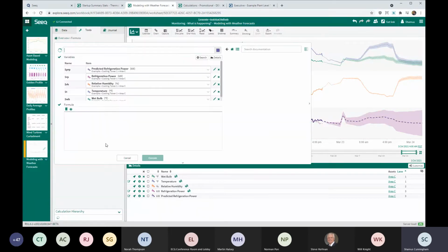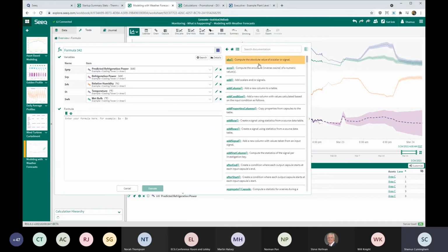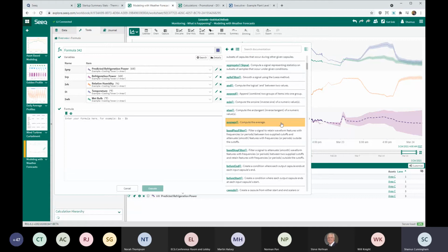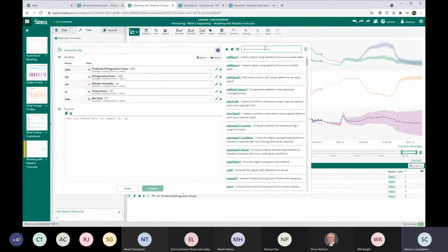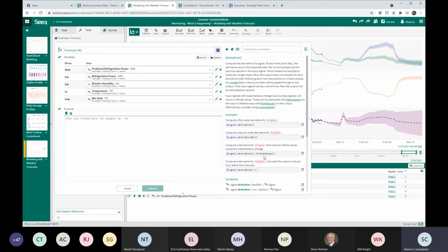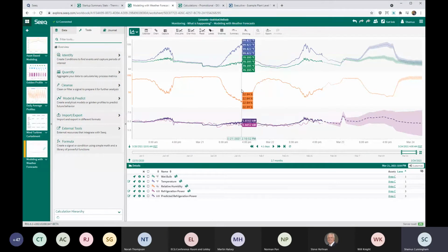we realize we're not going to build point-and-click tools for everything everybody wants to do. And so we also have a really nice formula language in here that codes exactly like Excel and has about 300 different functions that everyone should feel nice and familiar with. Things that Excel has and things you wish Excel always had, like derivatives, and a bunch of documentation. So it's a nice, easy, self-service way to create live virtual PI tags. Users can take all these different tools to perform live calculations on their data.